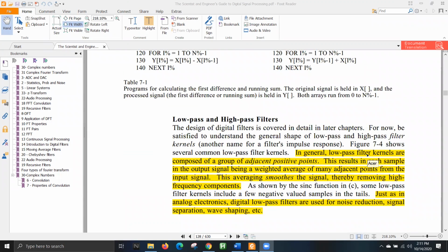Okay, and also convolution allows you to design filters. So when we actually perform filtering on any input signal, what we are really doing is just performing convolution of the input signal with some h[n], and that h[n] will basically define whether this filtering is a low pass filtering or a high pass filtering or whatever type of filtering it is.